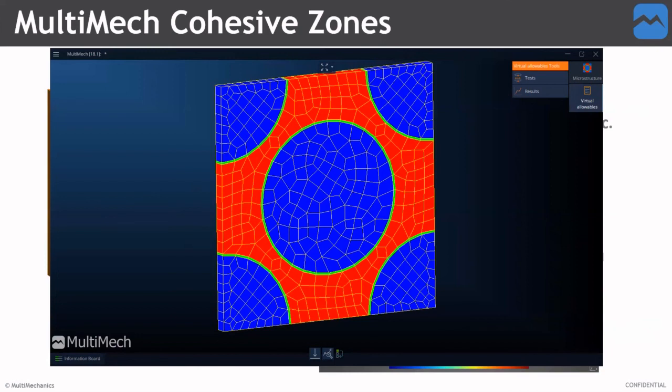But of course, this isn't the only application. We can do things, for example, for adhesives. So if we want to study how debonding occurs through certain different adhesives, you can look at seeing how the thickness of the adhesive, are we getting adhesive or cohesive failure? And we can do this by experimenting with these multiscale cohesive zones and seeing how cracks propagate. And you can even go as far to put a cohesive zone around a multiscale cohesive zone, so you can see if the crack will propagate through the microstructure or adhesive failure, or it'll debond with the adhesive on the side, which is more on the interface. So you can do things like that to really see how you can improve your adhesive and how you can force a more tortuous crack path and get more fracture energy, or whatever you're trying to design your material for.